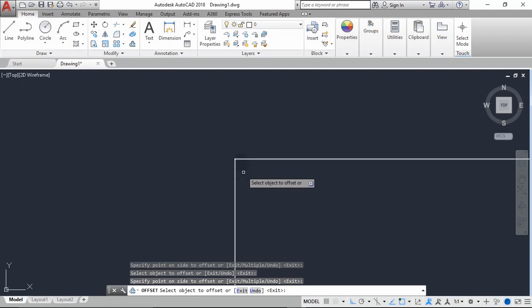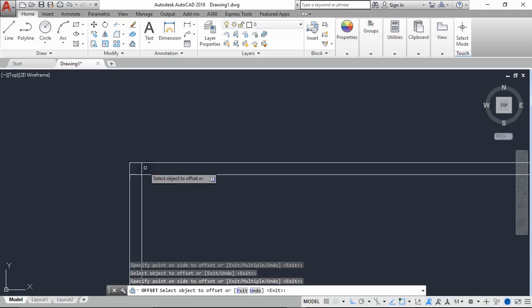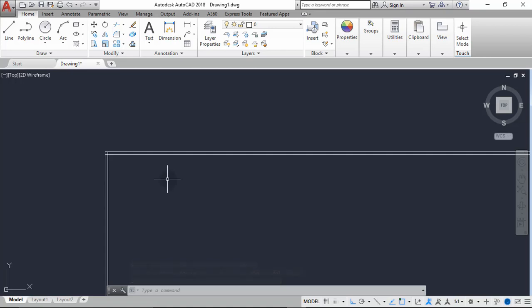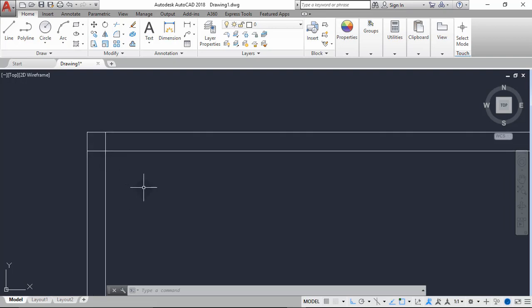So it's now looking like it's very tiny, but don't worry, it's better this way. Offset another 225. One thing we have to understand again is that in architectural design, in floor plan design, the way we do our dimensioning is there's outside out to out dimensioning and in to in dimensioning. The dimension I gave to us is in to in dimensioning, and it will only give us the dimension of the room excluding the block. So from here now, I'll start to give the dimension for my kitchen, and like I said, the dimension is in to in.